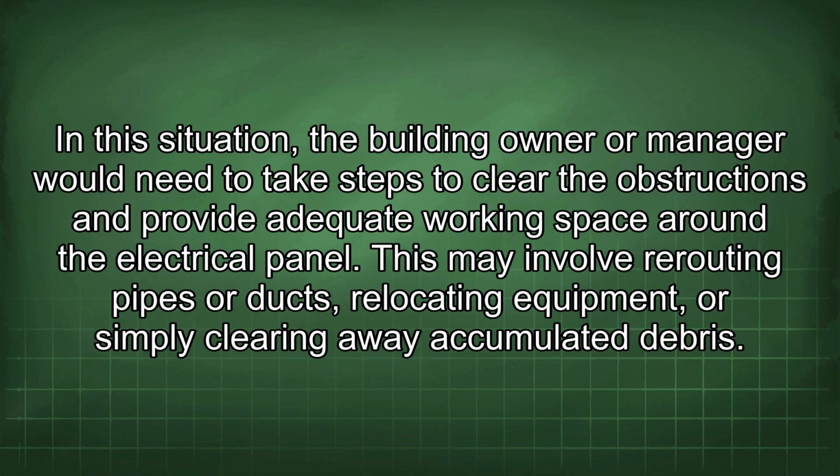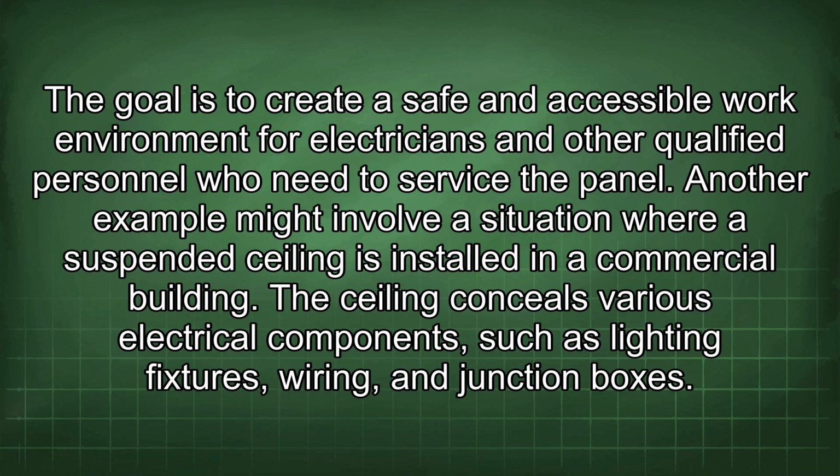In this situation, the building owner or manager would need to take steps to clear the obstructions and provide adequate working space around the electrical panel. This may involve rerouting pipes or ducts, relocating equipment, or simply clearing away accumulated debris.